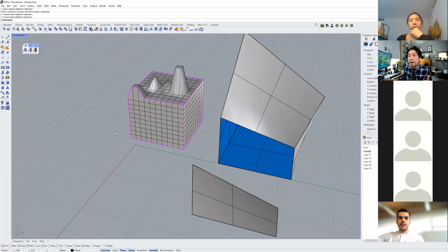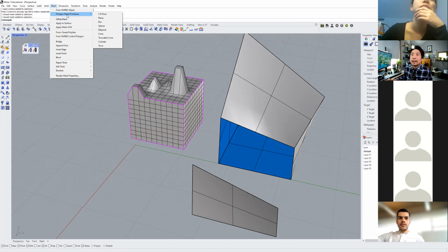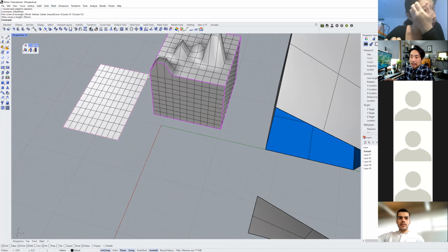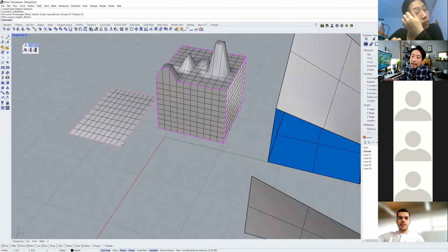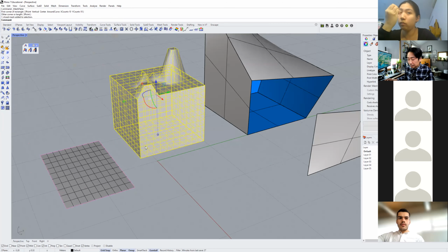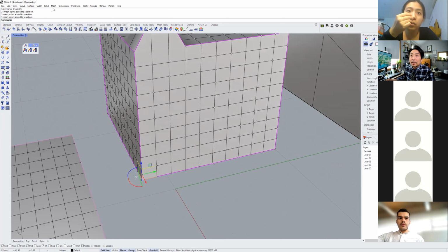So you have such a thing that's called a naked edge when you're creating mesh surfaces. Okay, so a naked edge means the edges are exposed to nothing, right? So in this case, here is another edge, but the edges are actually touching the other surfaces. So these are not naked, so they have slightly different color. But edges can also be welded together.